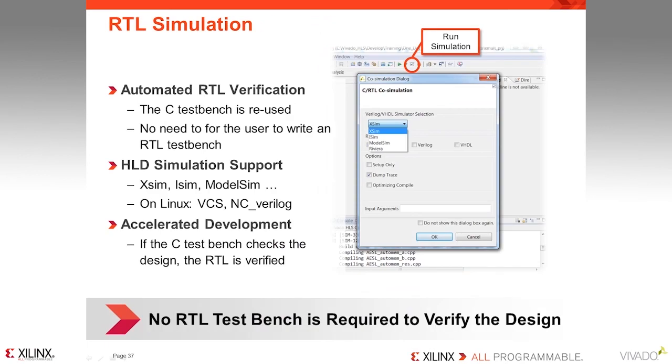The other thing that Vivado HLS does is RTL simulation. The great advantage here is that the user does not have to create an RTL test bench. So long as the C file exists and can be simulated in C, Vivado HLS will take that C file and automatically create an RTL test bench based on the stimuli from the C input.